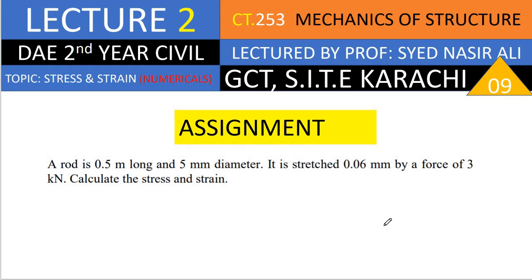This is the assignment. A rod is 0.5 meter long and 5 millimeter diameter. It is stretched 0.06 mm by a force of 3 kilonewton. Calculate the stress and strain.